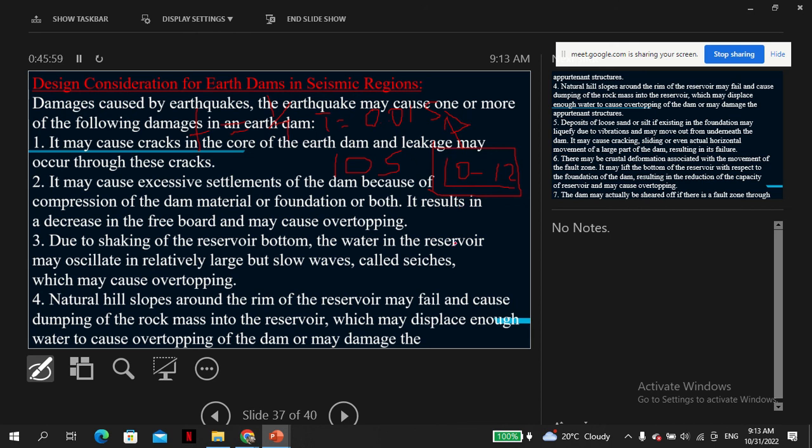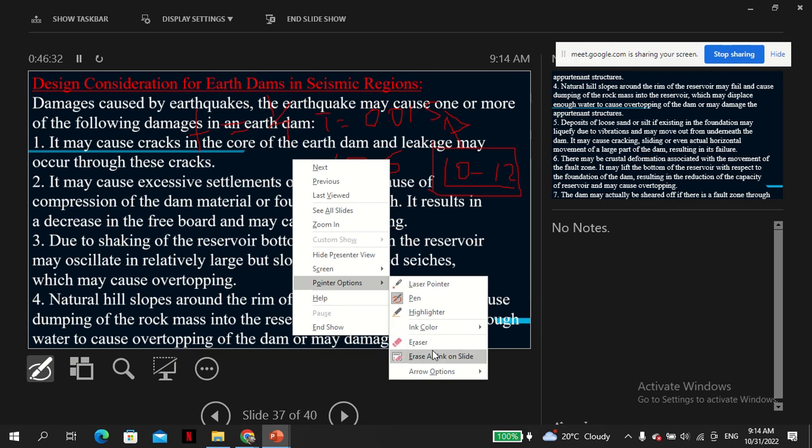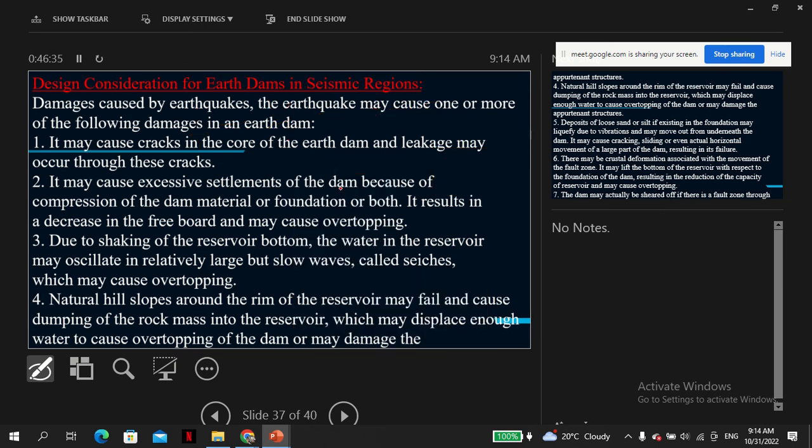So the frequencies of 10 to 12 story buildings are in the range of the earthquake, and that causes resonance, and that always destroyed these kinds of buildings. And so in their codes they put some restriction. In fact, in the city code, you do not build houses in this range. You either do 8 and below or 15 and above, because of safety concerns of resonance. This was not to be done. Okay, so this is just to highlight how important some of these factors are.